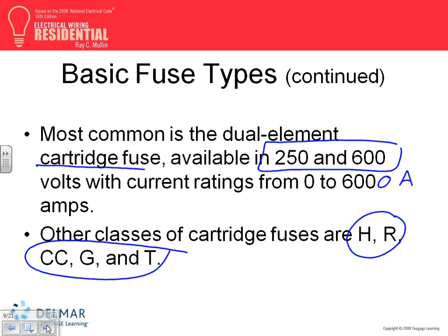Do you know the difference on the fuses, like the S in there? Well, the little S is there because they don't want you to put a 20 amp fuse in the slot of a 15 amp and overfuse.